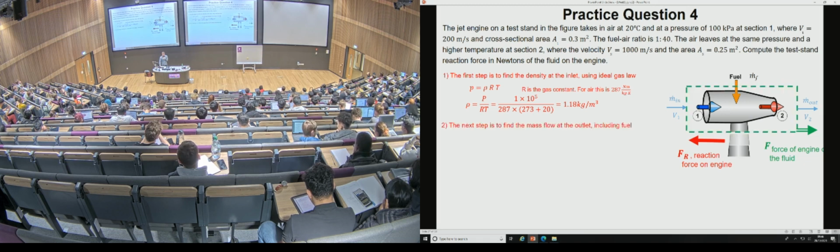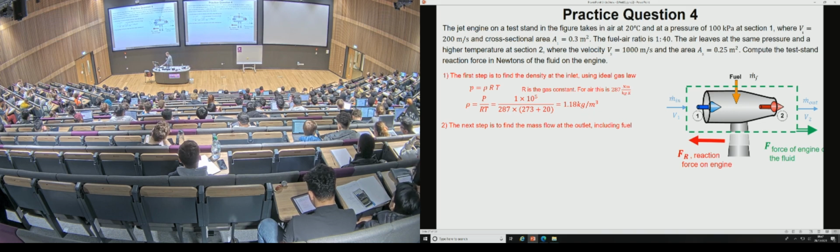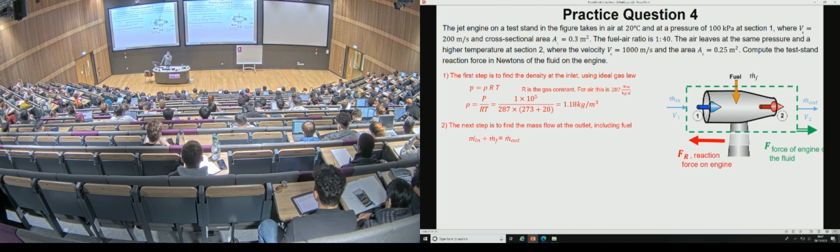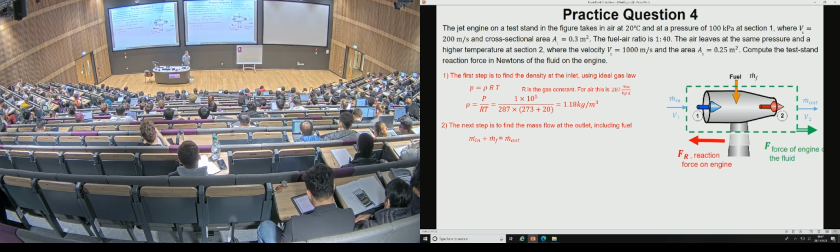and then you can apply your control volume analysis. So we're here applying our green dashed box around the inlet and outlet, but also the inflow of the fuel. So our conservation of mass equation now looks like this. It has an extra term because there's a source term. Mass flow going in, mass flow going out, plus the source. It's still essentially a 1D problem. It doesn't really matter what the direction of the mass flow coming in from the fuel line is. Just treat it as a source. At this stage, we can still treat this as a 1D problem.